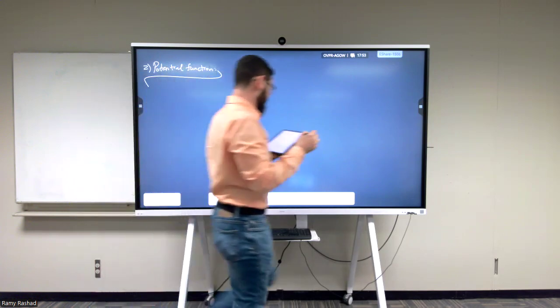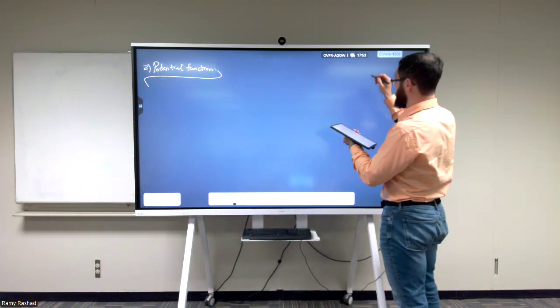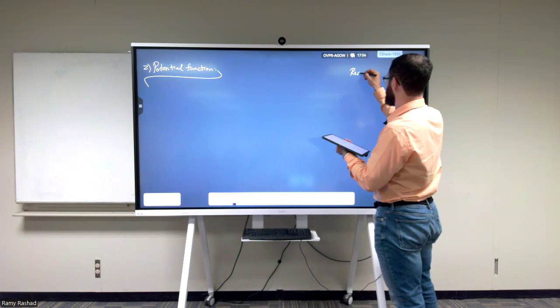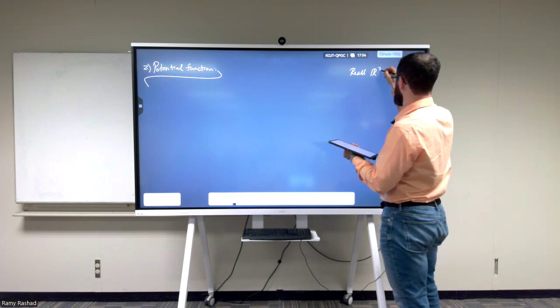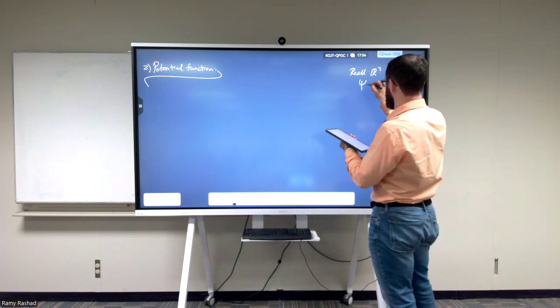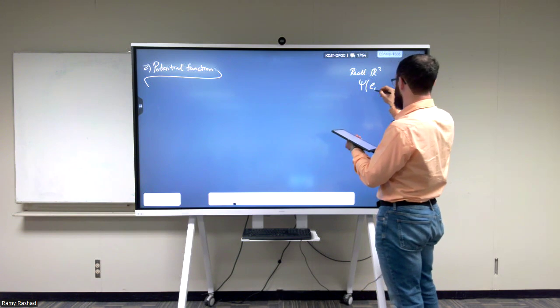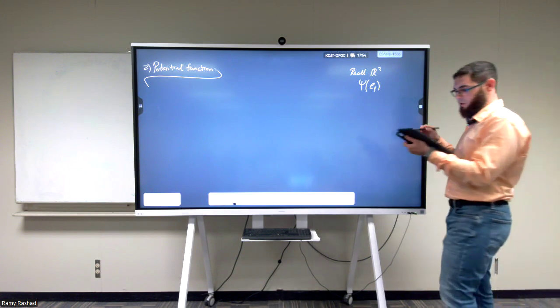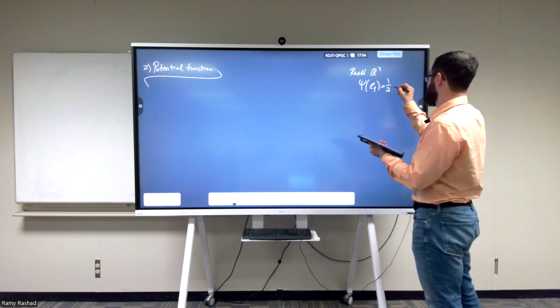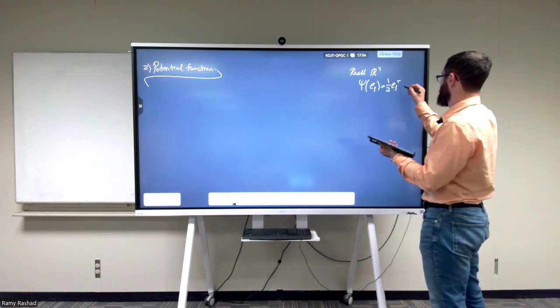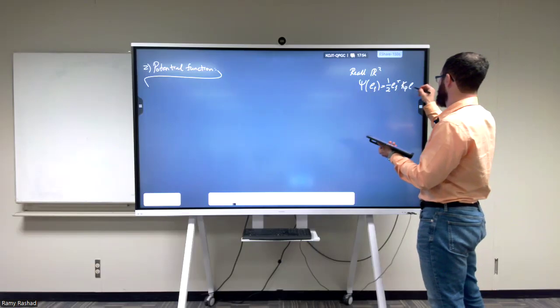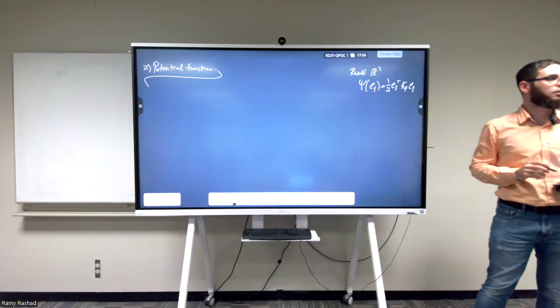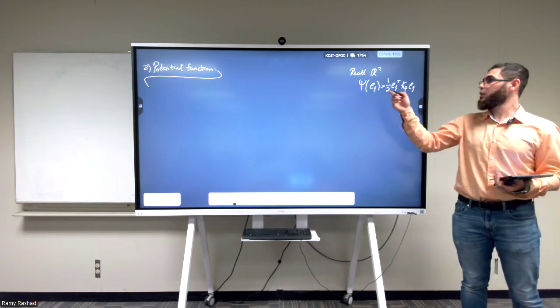Just as a side point, remember that when we discussed the case of R^3, we said that our potential function as a function of the error between psi and psi desired was a quadratic function. It looks like this: P of e_psi equals half e_psi transpose Kp e_psi. And this is written as a function of the error.